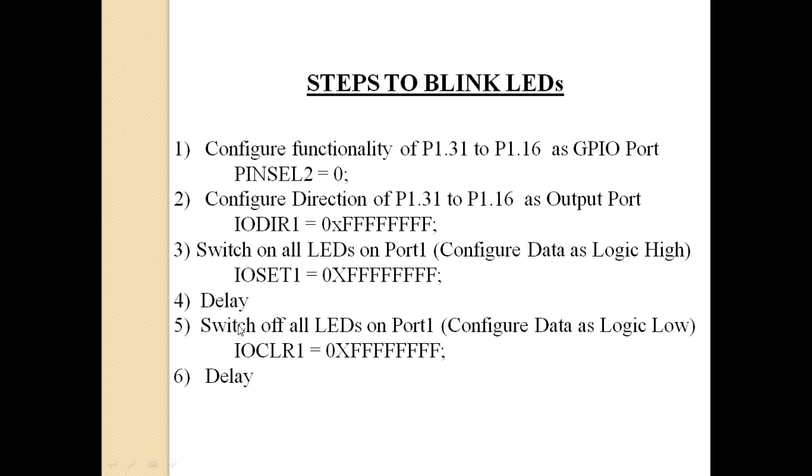Right? Then you need to switch off the LED. Again you should add a delay. Why is the second delay required? Otherwise, after switching off, again it will go to switch on, and you will see that it is on always. So for LED blinking, you need to write all these 6 steps, right?